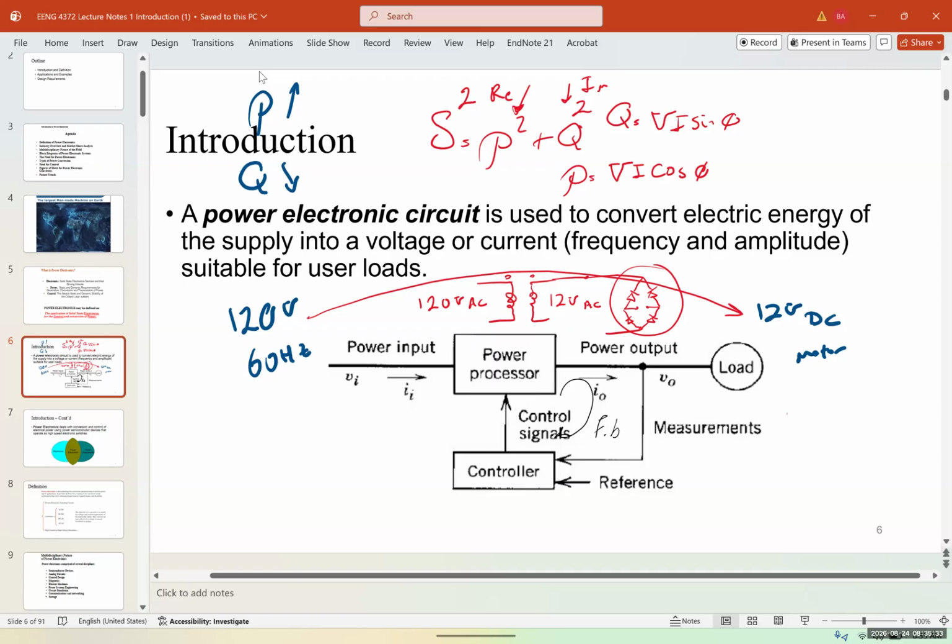Now, the measurement that we do here is we can measure voltage, current, or frequency. I'll explain why. If we have an AC to AC converter, sometimes we don't want to change the voltage from the input or the output. We want to change the frequency. One example is, imagine we want to connect Europe to the US grid. It's a different frequency, so you definitely need an AC to AC converter to match those frequencies, which is a tremendous and difficult task, not that easy.